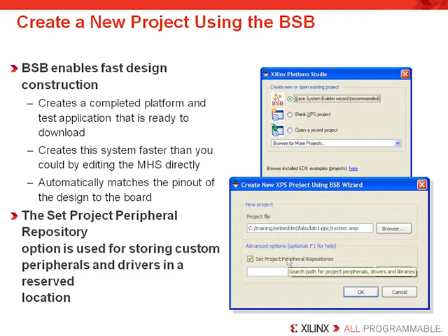The UCF file also contains your design's timing constraints. These are used to communicate to the implementation tools how fast you want the parts of your design to operate, and most specifically it's going to make a global constraint for each of the clock domains. So if your processor system has two different clock domains, one for buses and peripherals and one for the processor, then the tools are going to have a timing constraint associated with each when you use the BSB. So this is a good thing. It's going to save a lot of effort and a lot of understanding.